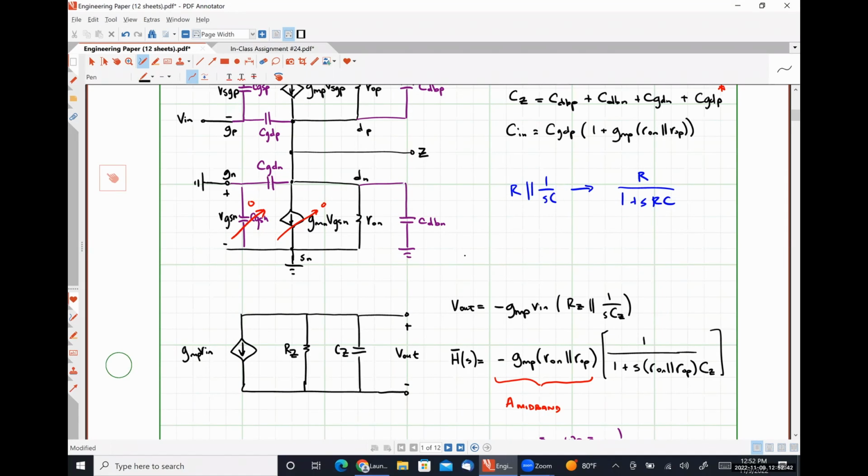So we're referring some portion of this capacitor to the output of our differential stage, thereby making that CY even larger and pushing the location of that pole closer towards 0 hertz or 0 radians per second. Understanding the influence of this capacitance is going to come into play when we talk about intentionally compensating things.